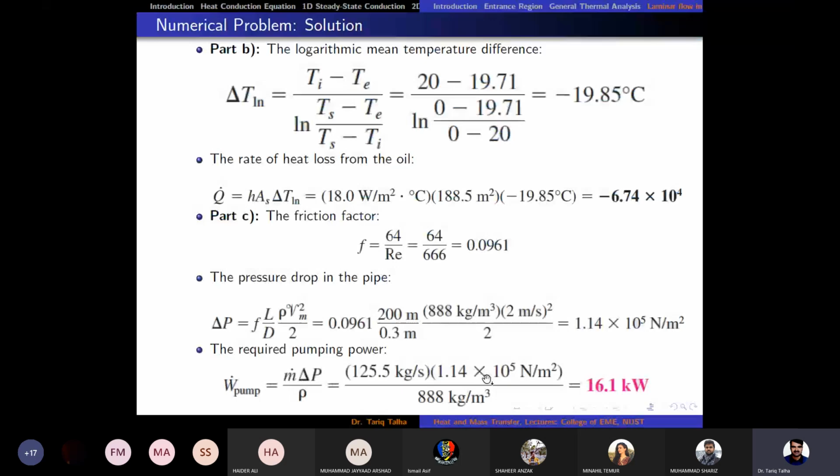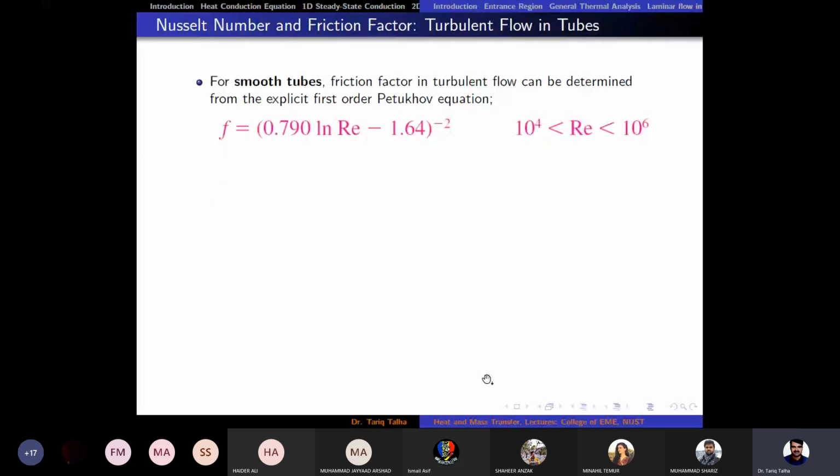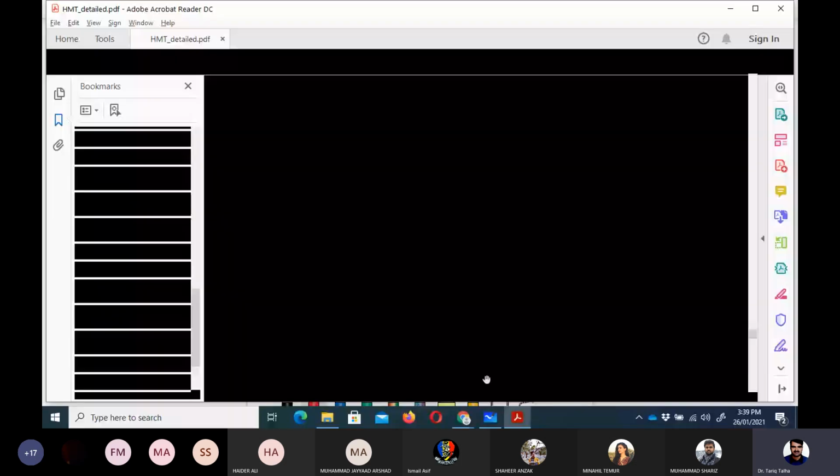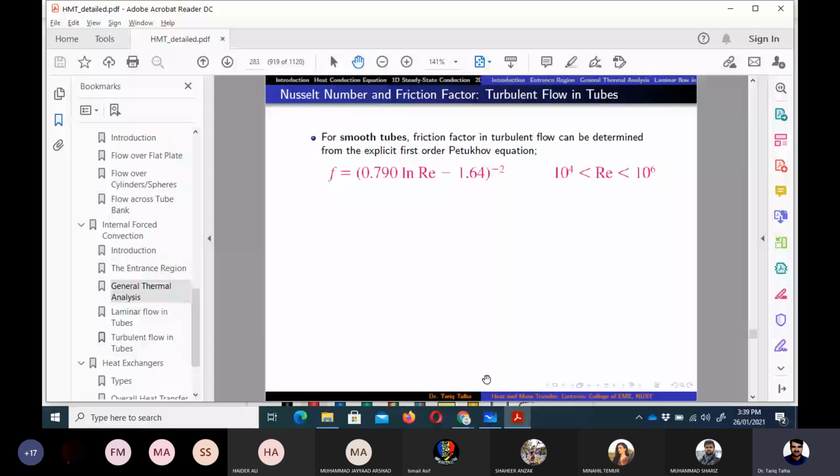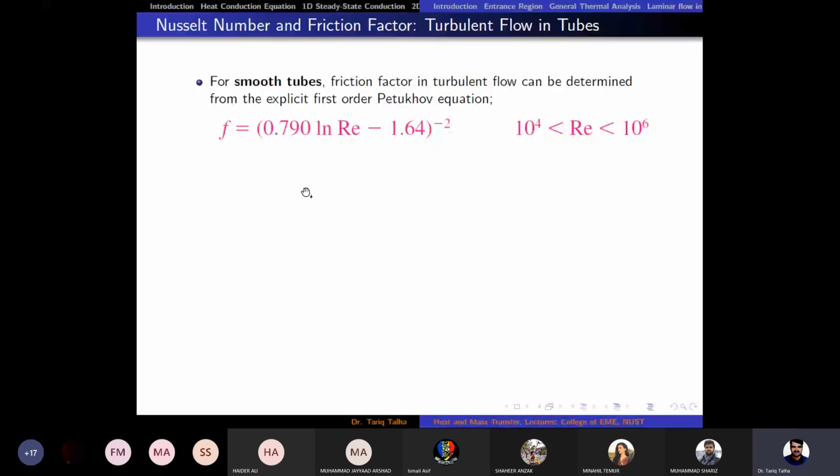First of all, if we talk about the transitional flow, and we still say that we are talking about smooth tubes, meaning we have polished or machined them to a very fine scale, then for that case the friction factor is again only dependent upon Reynolds number. There is no mention of surface roughness, because we are saying that the pipe surface is highly finished.